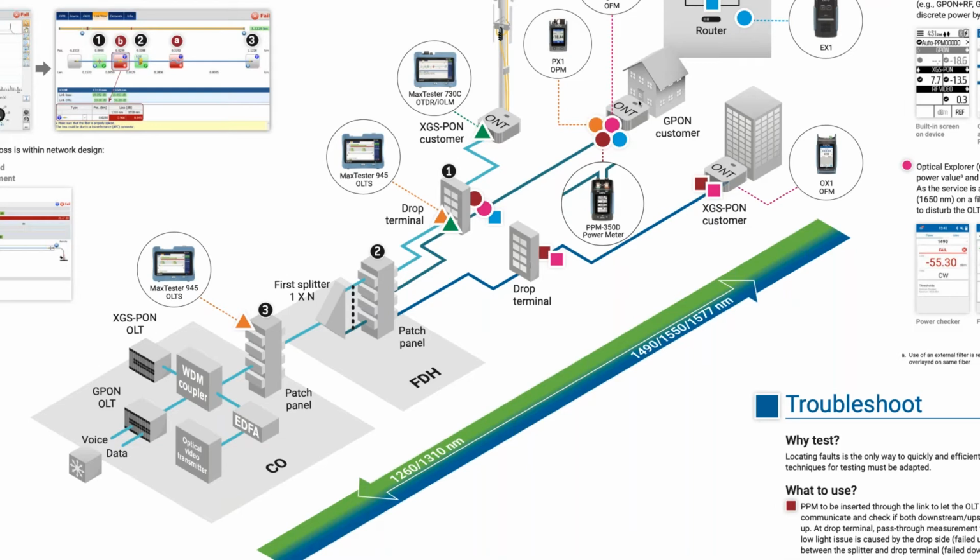Yes. On the OTDR, it's going to look very confusing to the uninitiated, especially if you don't know exactly the split ratios. But if you're utilizing IOLM and you at least give it the information that you're shooting through a PON network, you'll get much better and more accurate results because we're using multiple pulse widths, and we'll be able to get them out of a single shot.